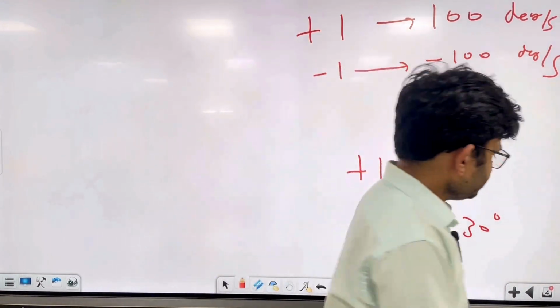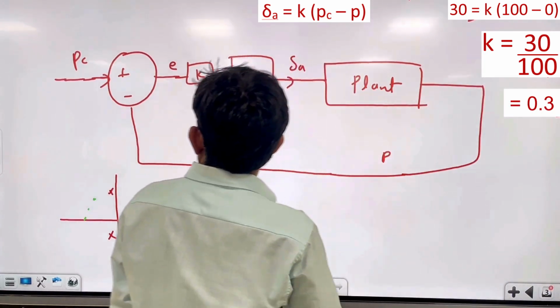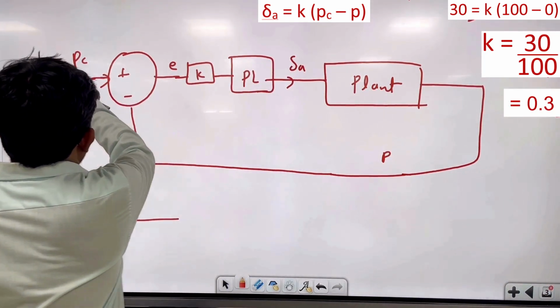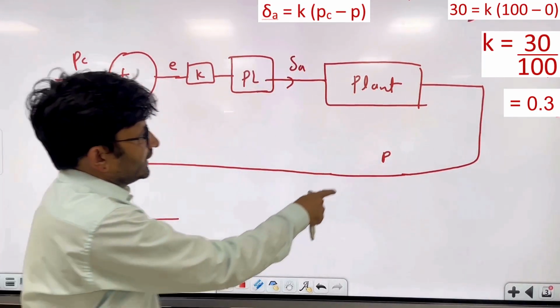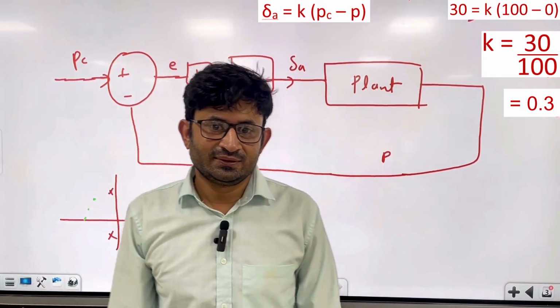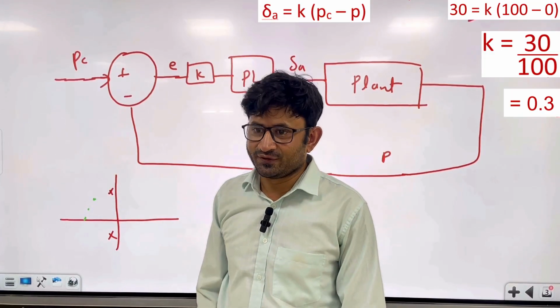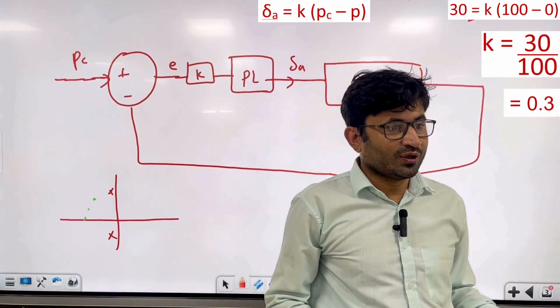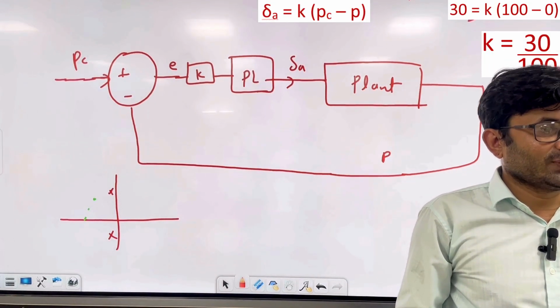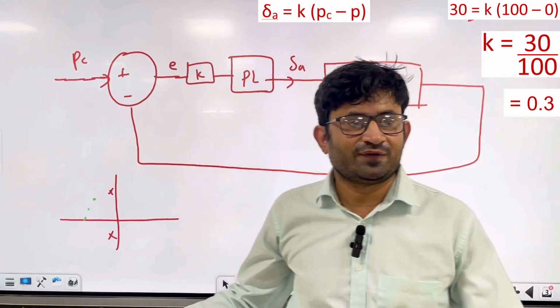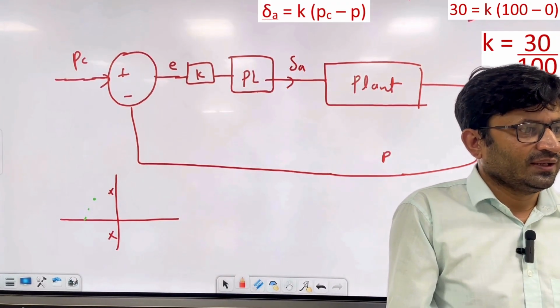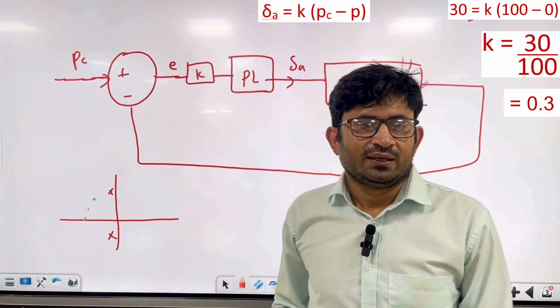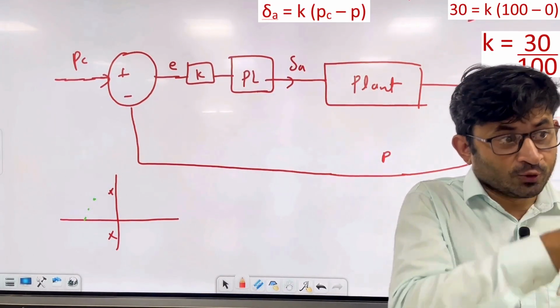Now, when you give the Q command here, you will take Q feedback, this aileron becomes elevator, right? Similarly for the rudder case. So now you can see in rate mode, by deflecting the stick, your rate is generated and you are actually flying. So you will have less workload compared to the last one, which was the true manual mode.